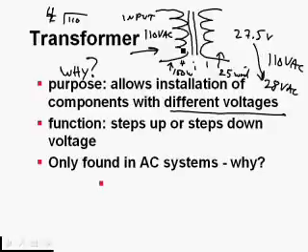So with a step-down transformer in an aircraft that's already producing 110 volts alternating current, we could have a 4 to 1 step-down transformer, and all of a sudden we'd have 27.5 volts AC. And of course, we're pilots, we're going to round to the nearest whole number, 28 volts AC.